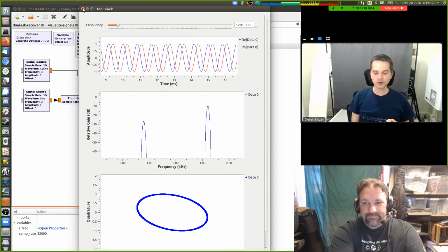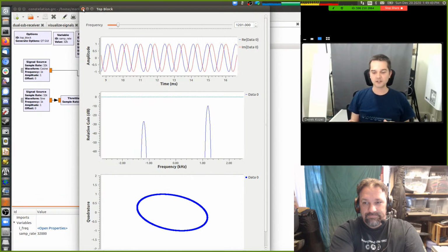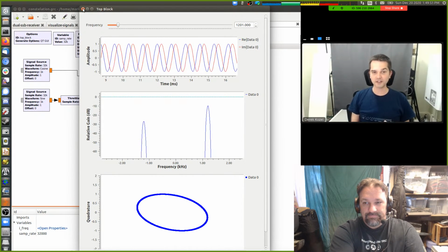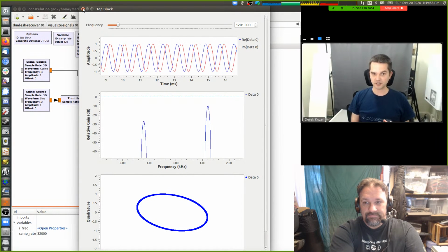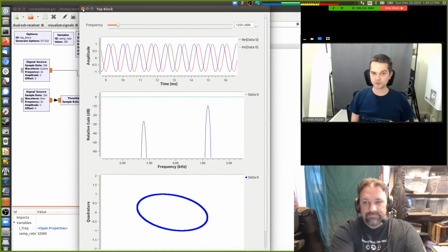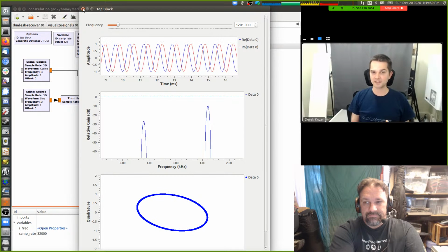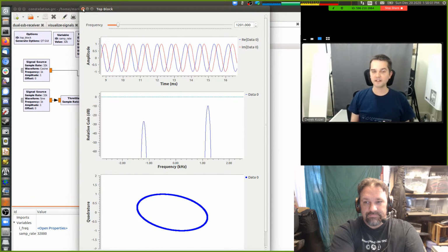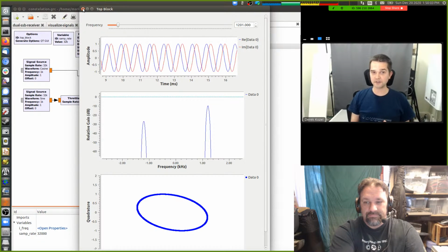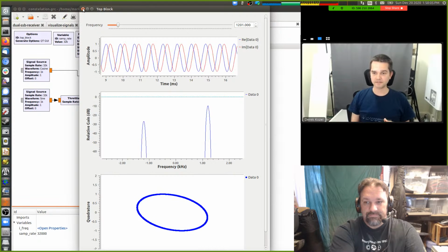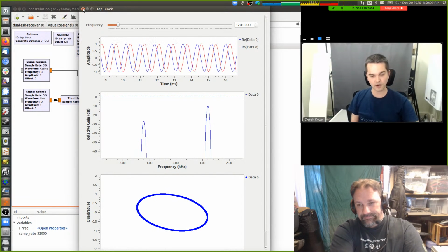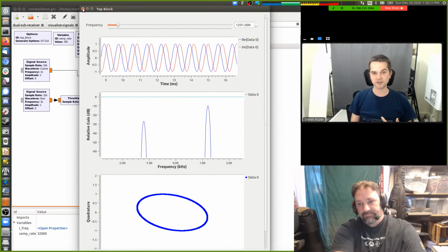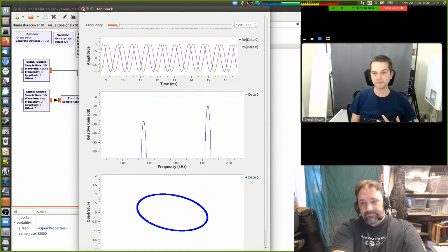If you are transmitting directly, you are not going through a local oscillator. It is sufficient, and you can transmit a single sideband signal with a real valued output. Sure. Because you are not doing any frequency conversions on that real valued signal.